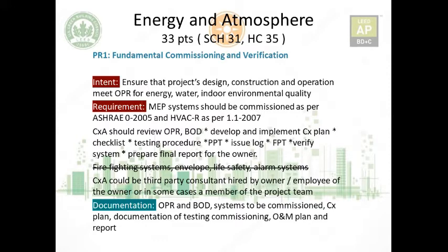The checklist is the same as the LEED scorecard. You have certain things that you need to confirm. You put them in a sort of list, and then you tick mark whatever is done or not done, or whatever your remarks are. Then come the testing procedures, standard procedure testing for MEP systems, including pre-functional performance testing, where the equipment or system is not fully functional, but you can still see the drawbacks or if there is anything missing, and you write it down in the issue log.